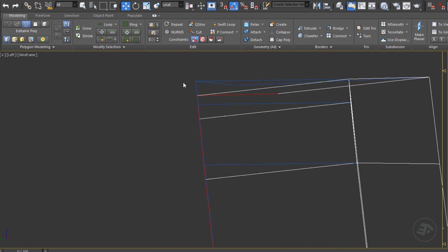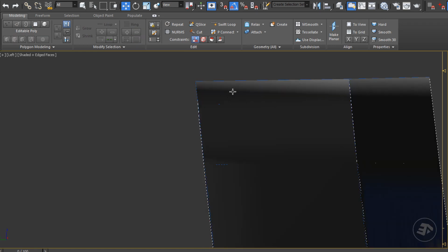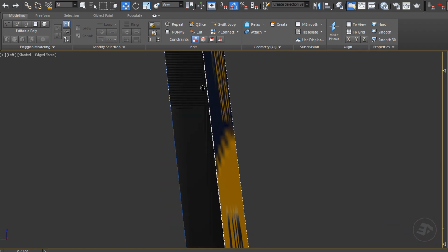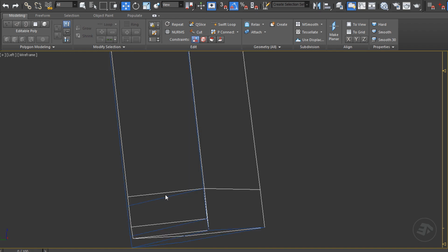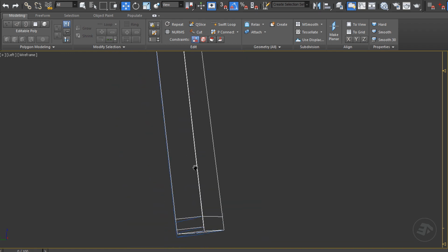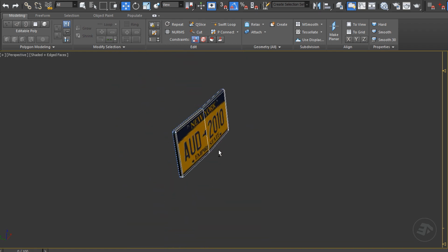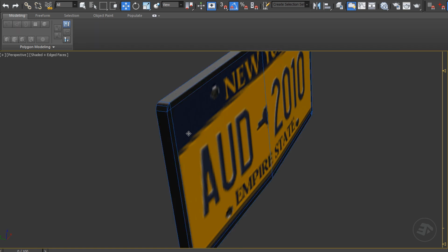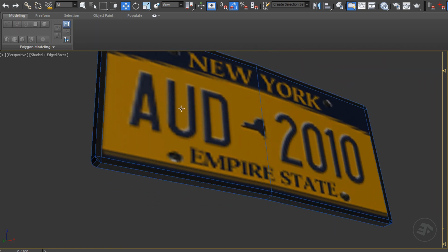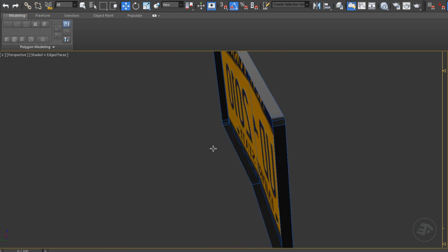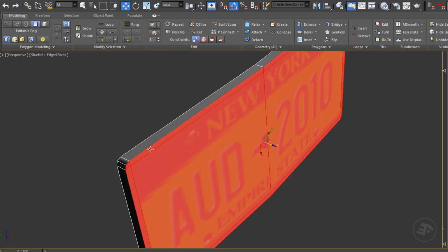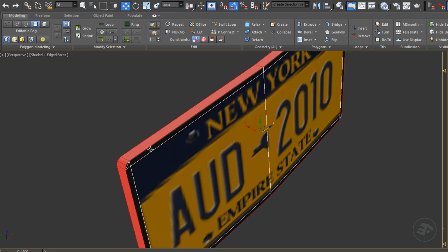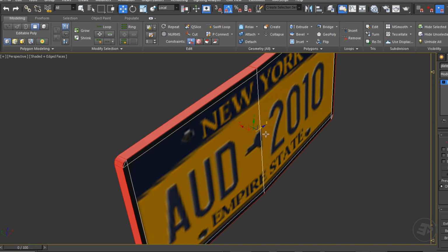We could match the new extrusion to the old frame by snapping vertices, given the fact that any manipulation of the license plate geometry will not affect the existing UV map. Now, I can take the old frame to a better place. As you can see, the texture misalignment has been fixed. Detach the extrusion to element, then apply smoothing groups to its polygons.